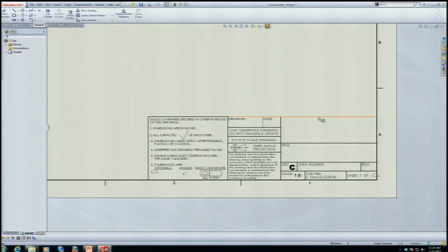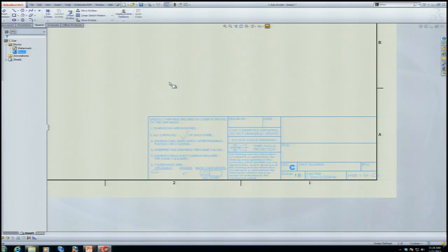Especially for title blocks like this. If you get more into sketch blocks and you need to start sharing sketch blocks across multiple designs, that's when you need to get into more detail. But if you look, now that I have a block here, that block is now represented there. I don't want to leave this as a block on my document. It's now a block. I'm going to rename it to title block.